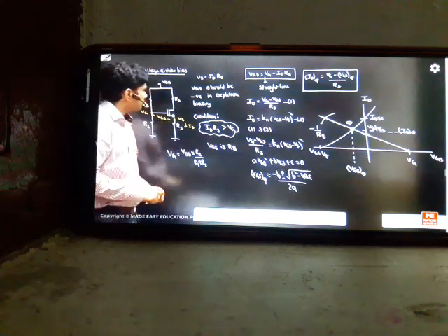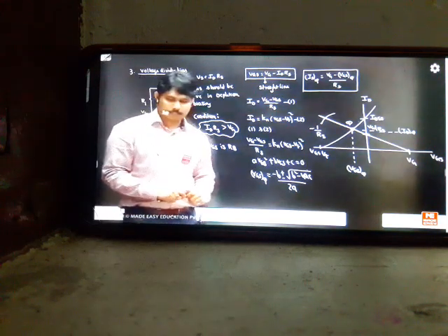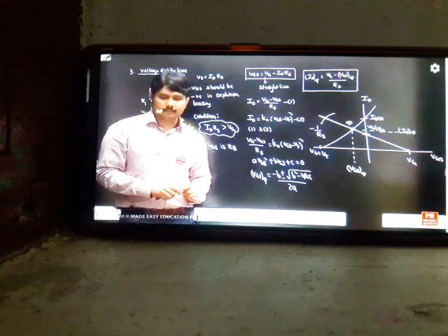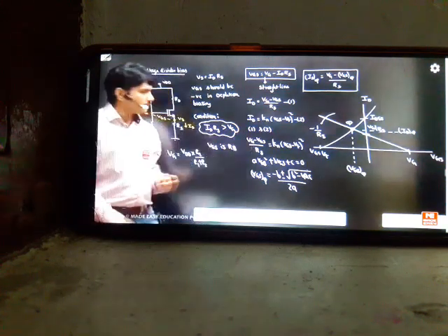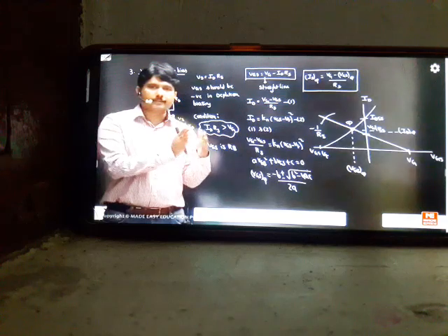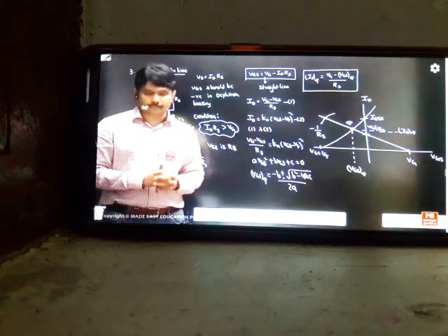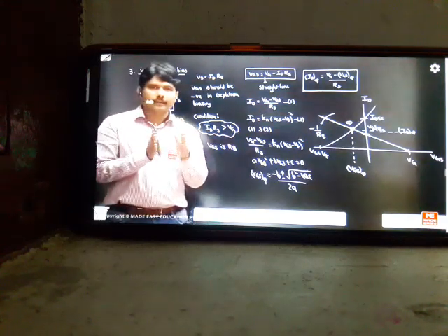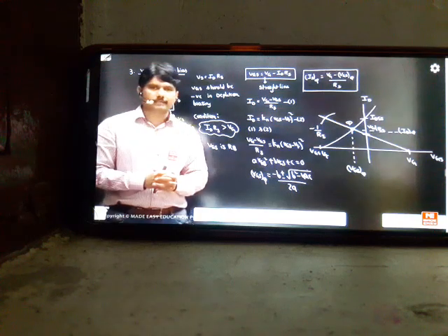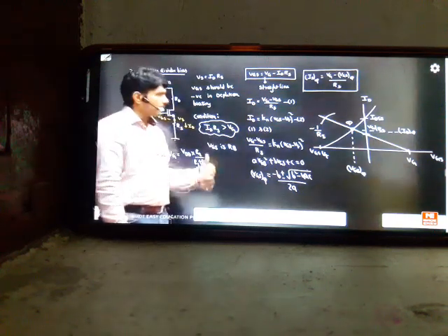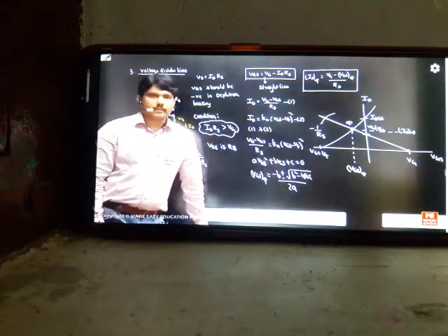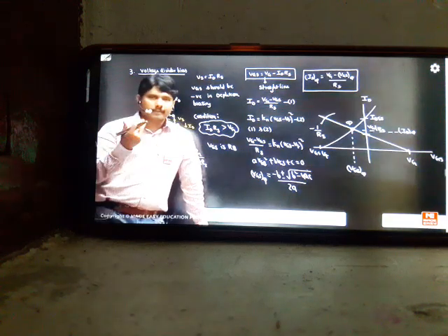Why is VGS negative? Satyam, what is the question here? VGS should be negative, why? Whenever VGS is negative, the system is under depletion mode of biasing. Because in depletion mode, VGS should be negative. Correct? VT is unknown, don't say like that. VT is not unknown. They'll give it in the exams. VT is compulsory, they'll give it in the exam. In depletion mode, they'll use some negative value of VT in the problem. In every question, VT is a default. Here I'm not showing it, but the examiner will give the VT value compulsorily.